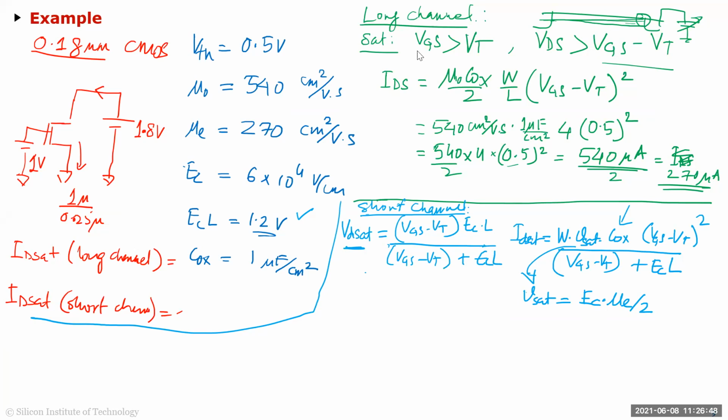Okay, like I just said, you have to do some sanity checks. So when you get answers, Shruti, when you get the answer 4.76 amp, you have made some unit mistakes, because first of all, we have calculated 270 microamps right before, and we know that because there is mobility degradation and velocity saturation, it's actually going to be lower than 270.